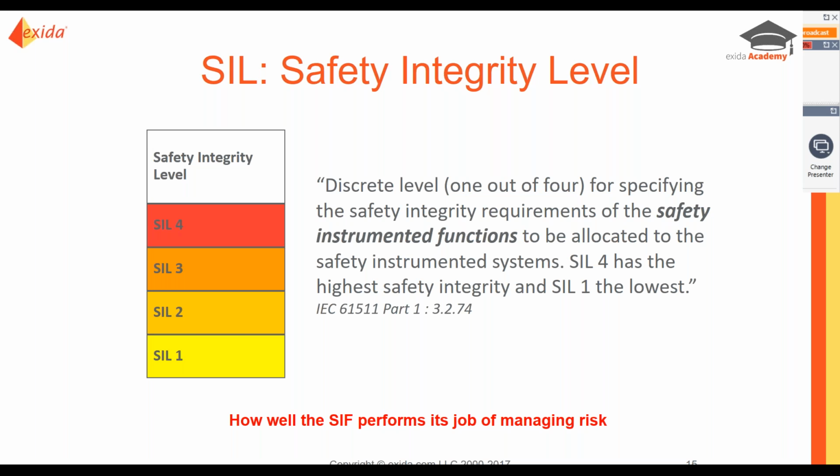And that doesn't mean that the products are not equivalent. That means that they were audited for more requirements, where SIL 3 had to meet the requirements for SIL 1, SIL 2, and SIL 3. It is possible that somebody just had not gone through the process to meet the other requirements.